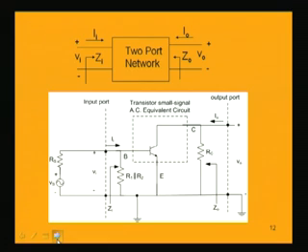So, basically now at this point the whole amplifier, after drawing the AC equivalent circuit, will be looking like this. Basically this source and resistance are there, this point is base, this point is emitter, we are taking a common emitter transistor, this is collector, this is emitter. So, circuits like a transistor are best expressed by a two-port system or two-port network, meaning those systems which have a pair of input circuit and a pair of output circuit terminals.